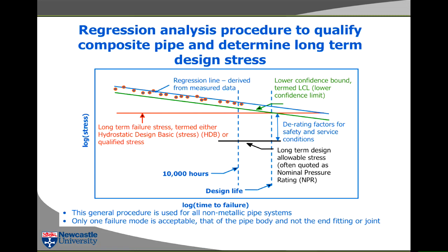Now, there are other factors applied to that, depending on the fluid which you're dealing with, the country, the rules of the place where you're installing the pipe. So there will be a further safety factor applied to that. But the HDB is the fundamental thing, the hydrostatic design basis, and that's this point here.